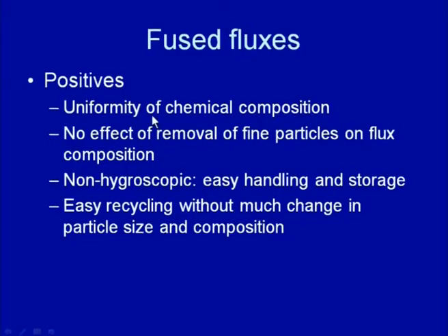The fused fluxes are the ones where we will first take up the positive sides. The important thing with the fused fluxes is the uniformity in the chemical composition. So, here the uniformity is much better in the fused fluxes than the other types of fluxes, and further, if the fine particles in these fluxes are removed, there will not be much effect on the composition of the fused fluxes.